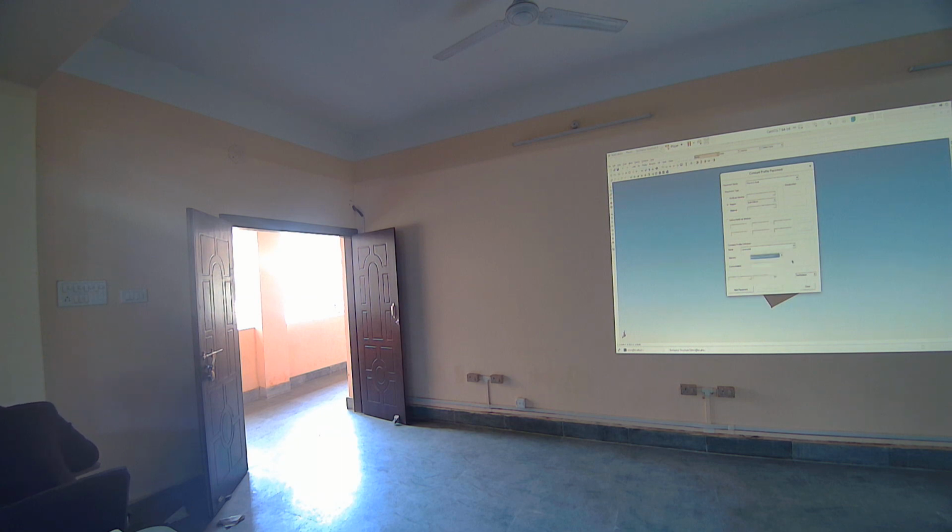I need to add boron kind of doping strength, right? According to this concentration, I can add whatever strength I want. So I'm adding 1E17 here, right? And once you click on this add placement, your constant doping will be successful in that particular region, sub-silicon. So I am clicking on this add placement, and now this doping has been done.